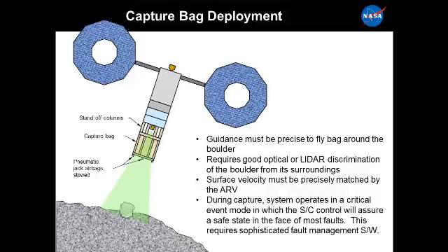But basically, you end up with a 2-meter or basically a 3-meter diameter capture volume with a bag that is stood off from the spacecraft by, say, a meter, with a more or less flexible inflatable stack column, depending on how flexible you want it to be. And you're looking down the center line with your sensors at the target as you approach. Obviously, this is a precision landing problem with reasonable precision, not really great precision.